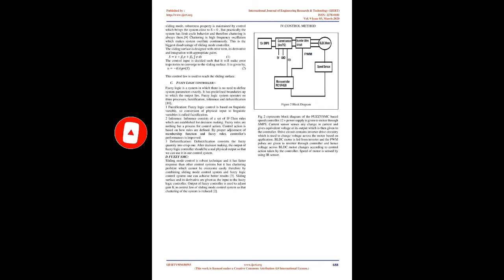3. Speed control technique. For speed control of BLDC motor there are many control systems developed like PI, FUZZY-PID, SMC, FUZZY, etc. The suitability of any control system depends on its response time, dynamic load conditions, robustness, and cost. The system which fulfills all these conditions is said to be a good control system.